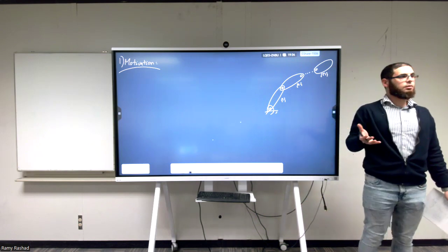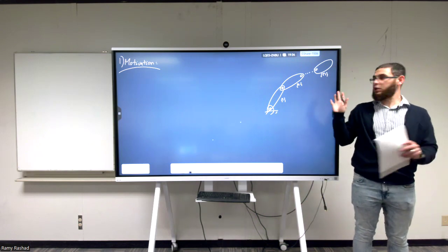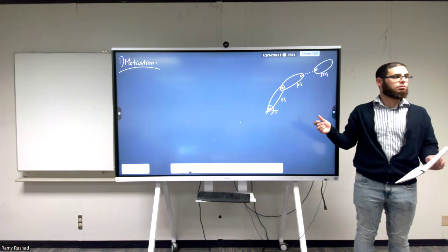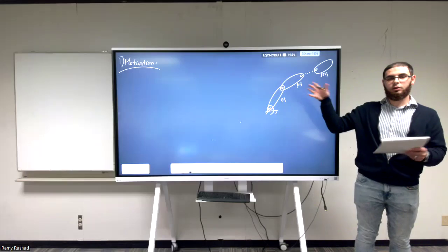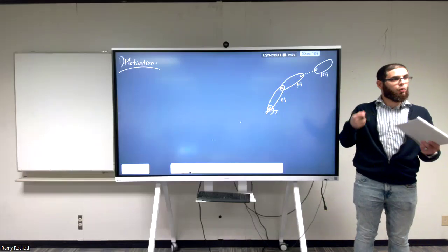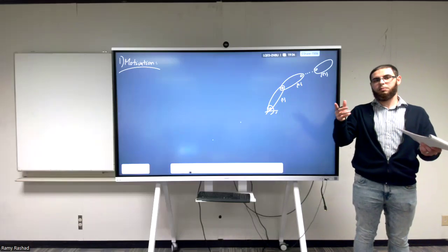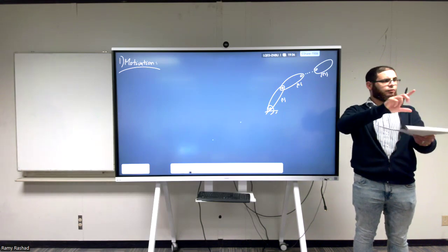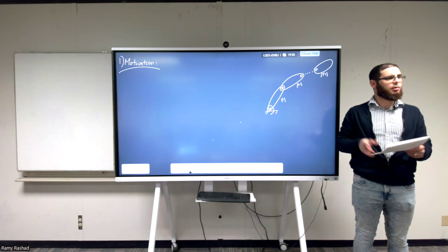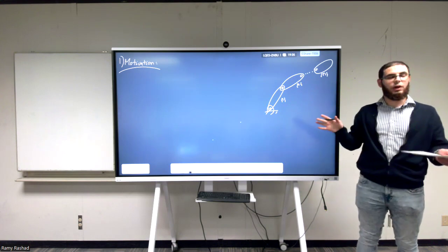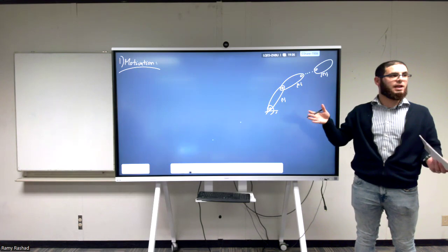And the way we start, the first thing that you start with when you see a robot like this is what? Frames, exactly. You should choose your reference frames. And the reference frames are completely arbitrary. With the tools that you learned, you're not bound to have the relative frames, or like having one frame related to another in some way. For example, like with the DH parameters, if you took that before. But we have full freedom in putting the frames as we wish.